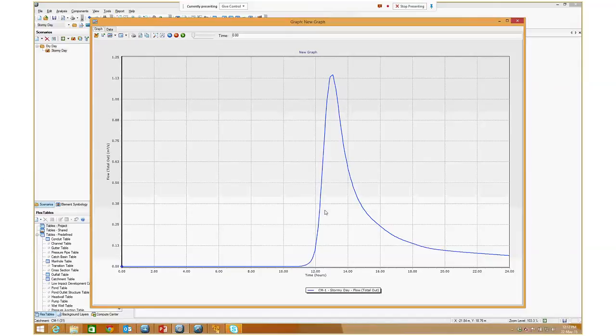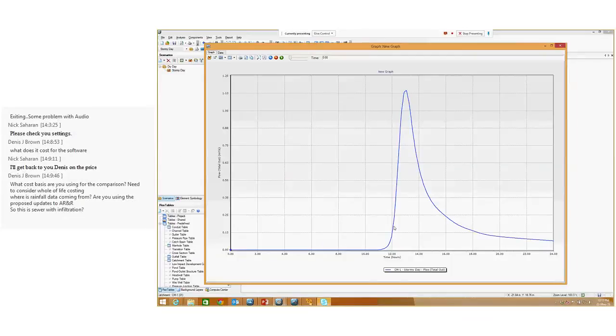Alternatively, a lot of water authorities will have rain gauges and so on out near their treatment plants, and they'll use that data. So pretty much any way you want to put it in there, whether you've got the data directly from the BOM, whether it's yours or rain gauges that you've got yourself. Either way, there's certainly a way to get it in there, and that's the flexibility of having 6 or 8 different methods. So this catchment here, you can see, as you'd expect,